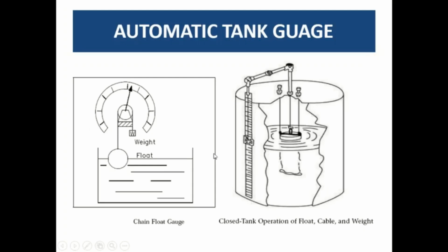After some time, when the liquid starts to fill up in the tank, due to the buoyancy force, the liquid won't allow this floating element to sink into the liquid. So this floating element remains at the surface of the liquid and moves upward as the level rises in the tank.